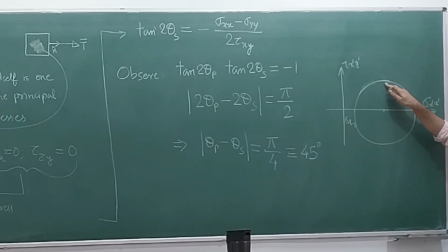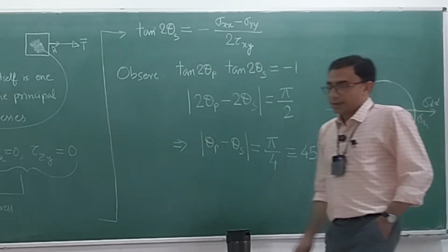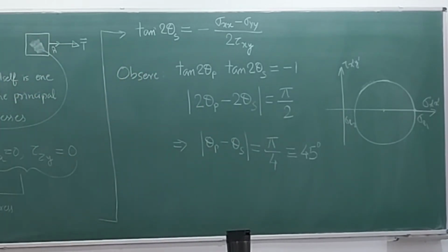It will be 0 in which condition? So this is a multiple choice question. Tell me, when is the normal stress corresponding to the maximum shear stress going to be 0? When sigma average is 0. When is that? When the center is at the origin. When the center is at the origin, what is happening to the sigma p1 and sigma p2? They are equal and opposite to each other. Okay, they are equal and opposite to each other. Very good. Now, let's discuss these things, that this 45 degrees and 90 degrees that we have discussed. Let's look at them geometrically.